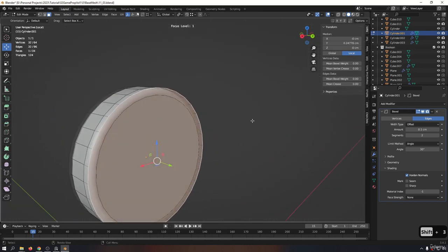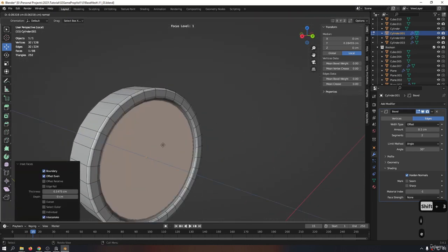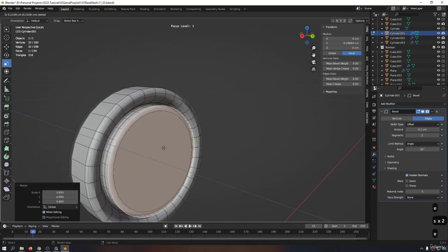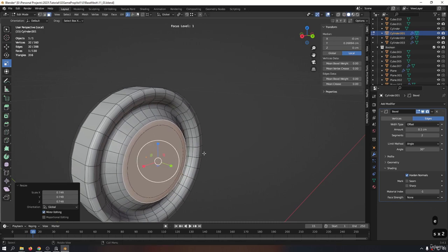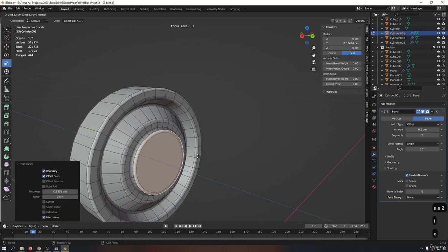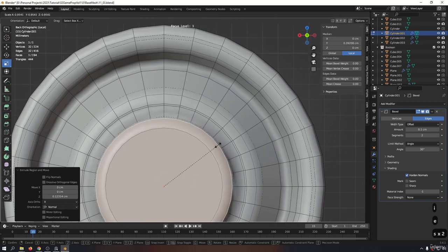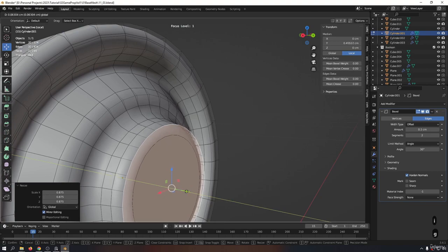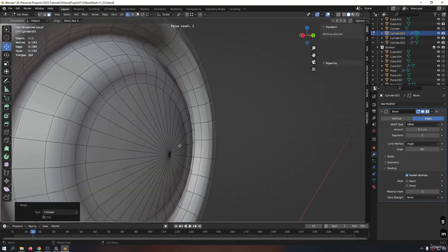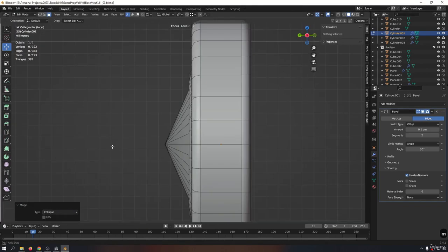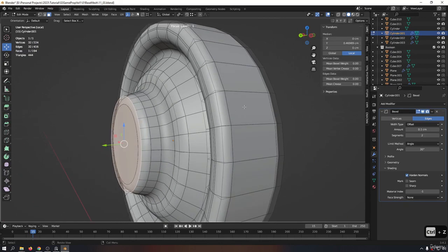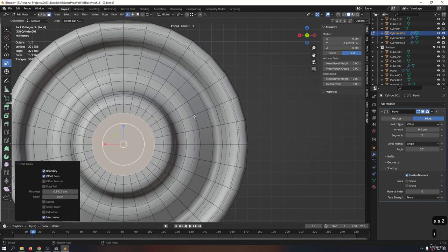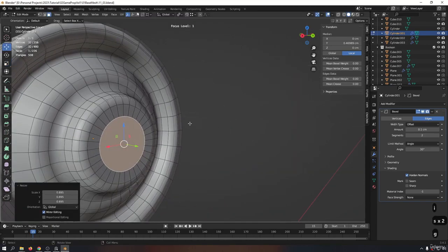I'm going to take these vertices, hit Inset, drag it back, scale it a bit, drag it up, okay, like so. Again, another Inset, drag it out, and then again Inset, bring the vertices out, M, and collapse. Or let's not collapse, I do not want that to be sharp. Let's just hit an Inset and rescale that, okay, like so.